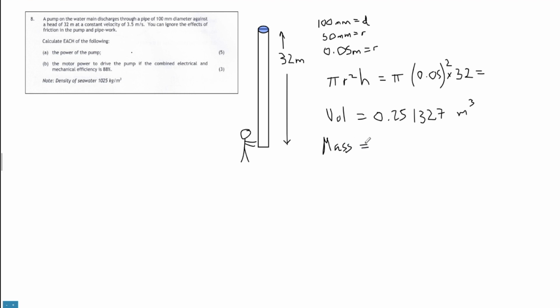Now, in order to get the weight of it, the mass of it, the mass will be the volume times by density. It's like the size of the thing times by how heavy it is. You can think about how big this thing is and times by how much it weighs. If it was polystyrene or styrofoam, it'd be really light. It doesn't matter how big the thing is, it'll be super light. But this is going to be pretty heavy, it's going to be a kilogram per liter, right? This thing's a meter cubed, so 1,000 liters. Anyway, let's plug it in.